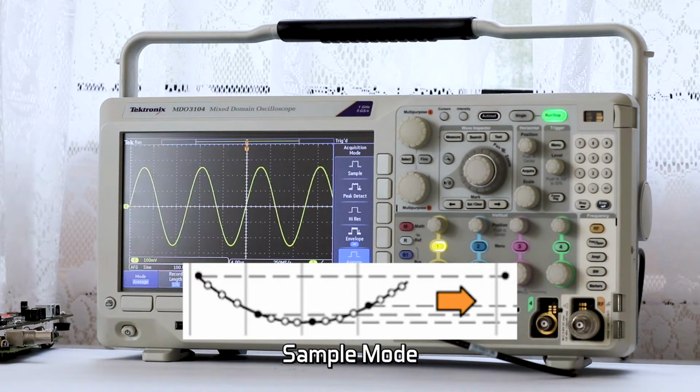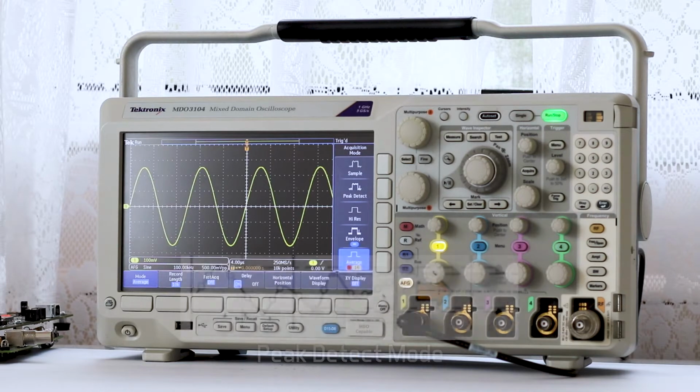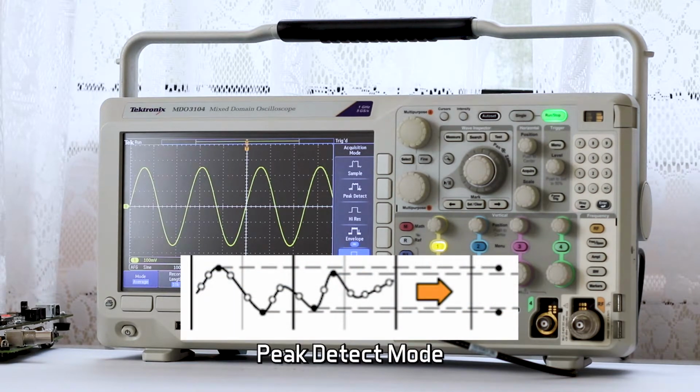Sample is the default mode, and it is the most basic. Peak Detect mode uses the highest and lowest of all samples contained in 2 consecutive acquisition intervals. This mode works only with real-time, non-interpolated sampling. It is used to display high-frequency glitches.